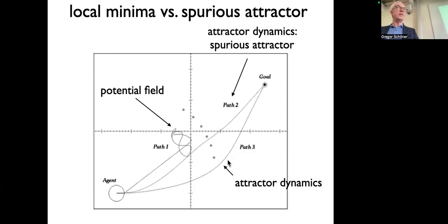We proposed actually a solution at the time. The solution was, in a case like this, to just select a few obstacles. In fact, to only select 2 obstacles, the ones with which you're most likely to collide, and let these figure out if you can pass between them or go around. And if you go around these 2, like here, and you have to decide to go around these 2, then you would maybe go in this direction, and then it switches, like now these 2 are the most colliding ones, and you would have to go around those, and so on. And that's a way to solve that.